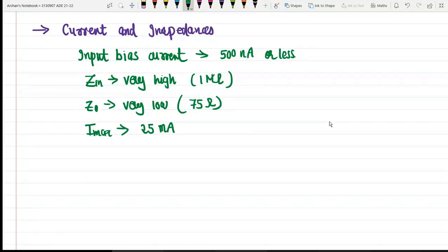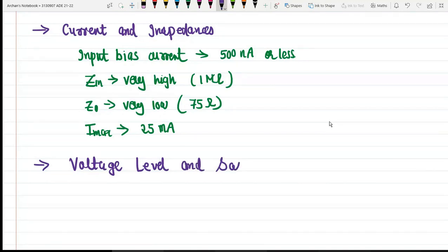You need to understand one term, which is the saturating property of the op-amp. Now, why is this important? We know that whenever an input is provided to the operational amplifier, according to the value of gain provided by this amplifier, my input signal will get amplified to a value very much higher than the input signal.